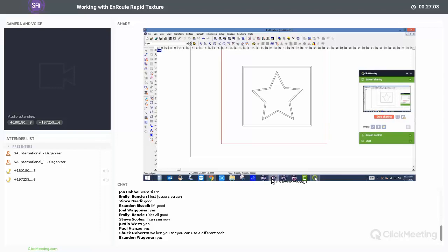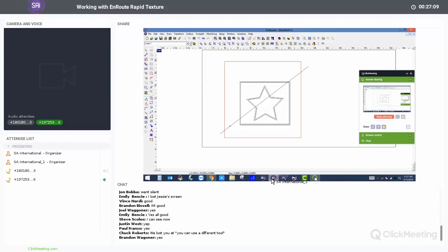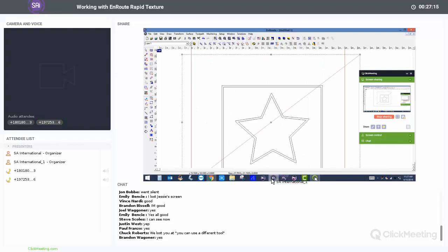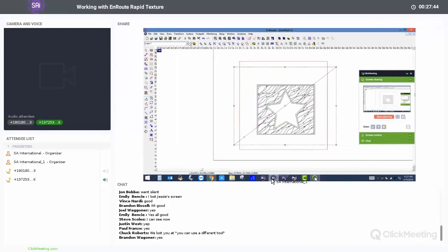So now what I'm going to do is create, instead of a closed geometry, an open one, just a simple line. I can use a closed or an open, but not both of them at the same time. So I'm going to use my open contour. I go into my texture. I want to make sure that my vertical amplitude is 1/8 inch, because that's what we offset. And also, whenever you're doing this kind of masking technique, you always want to make sure your overlap is set to 0. And then now we're just going to click on the area. So now it's this area here. Go ahead and click Apply. As you can see, we still get that random texture, but now it's going in almost that 45 diagonal.